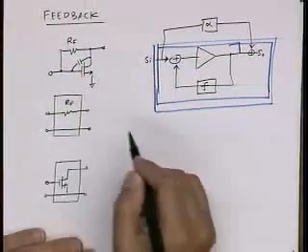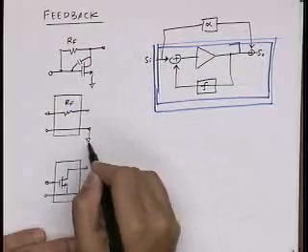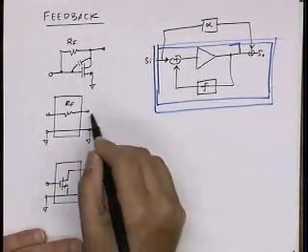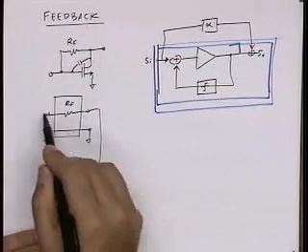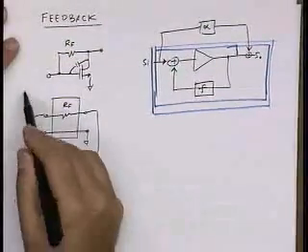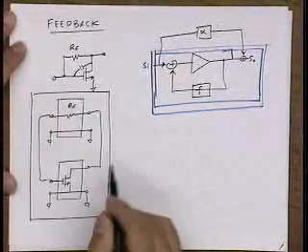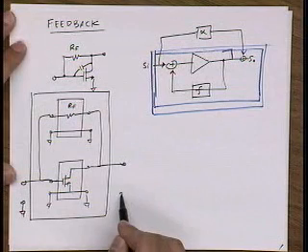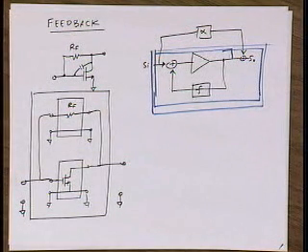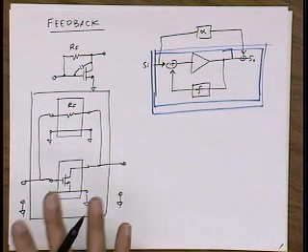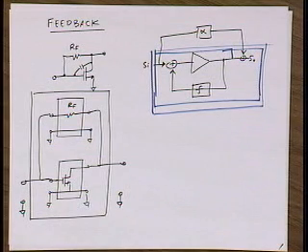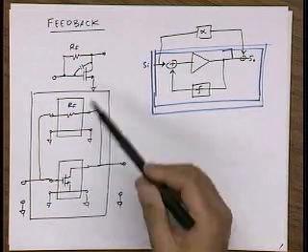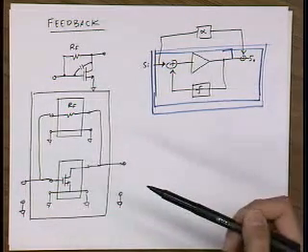Okay, so if I want to connect this in shunt, say I ground everything so I have a common reference ground here, and I just simply make a connection here and here. And now I have a new two-port that looks like this, reference to ground. Okay. And so now we know that a good way to analyze this problem is to use basically two-port parameters for the feedback network and the forward amplifier.